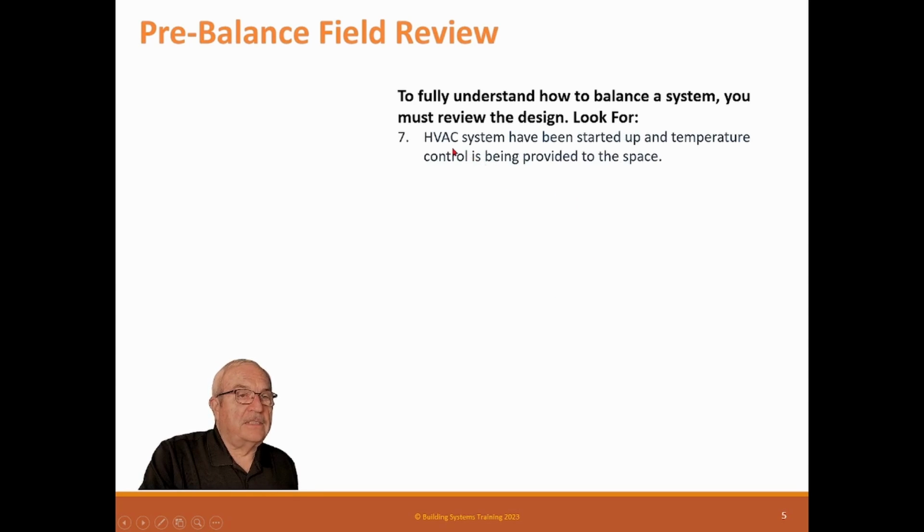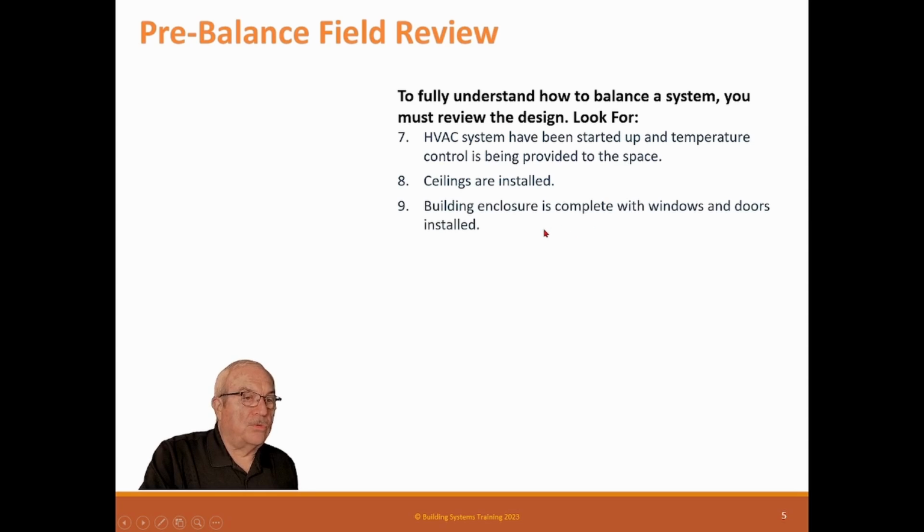So the next thing is the HVAC system is started up and temperature control is being provided to the space. The ceilings are installed. Building enclosures are complete with windows and doors installed. You can't balance a building for final pressure if it's not done.